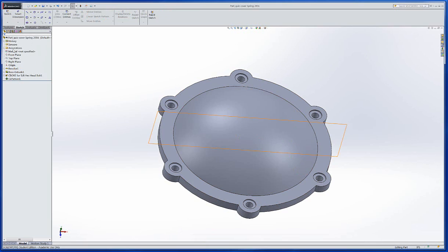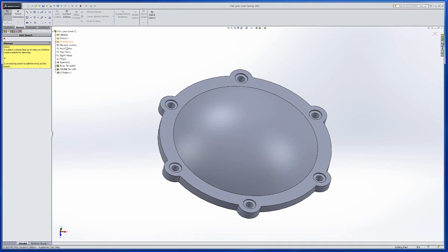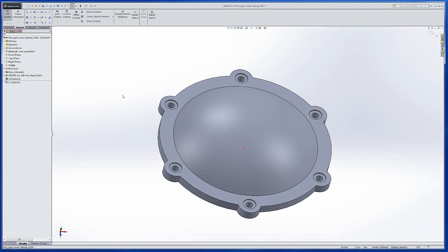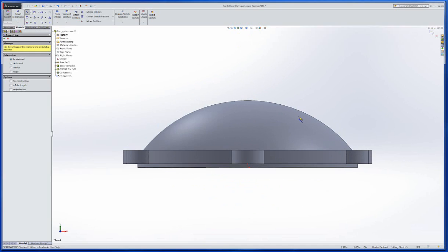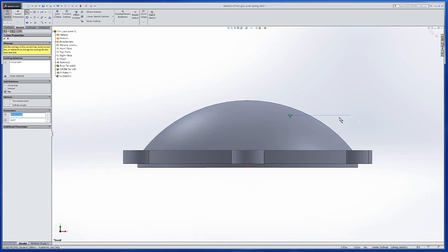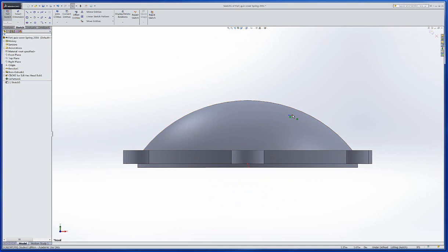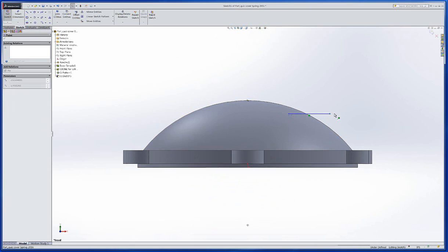Click over here and get the front plane. And I'll do a look at the normal. Then we'll draw that shape. Let's see, looks like it's going to be something like this. And I did it again. Somehow I get a double click there. It's the old guy thing.